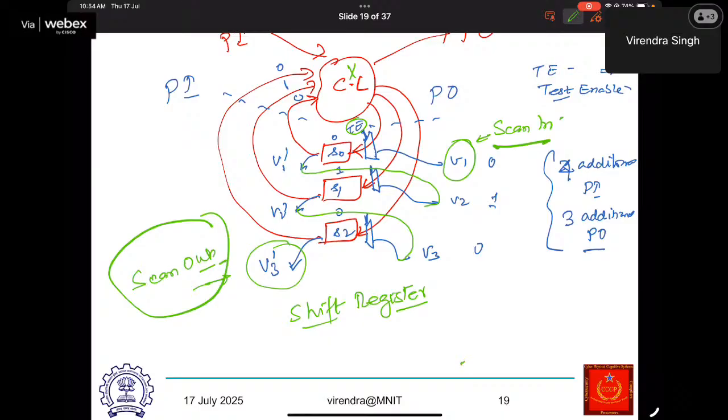And after initialization, I have to apply one test vector in one cycle, and then have to unload the output that I'm getting. Again, it will take 1 million cycles. So then total, to apply one particular test vector, it will take 2,000,001 cycles rather than one cycle.